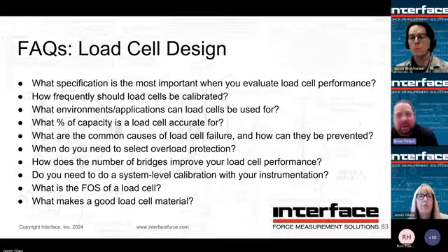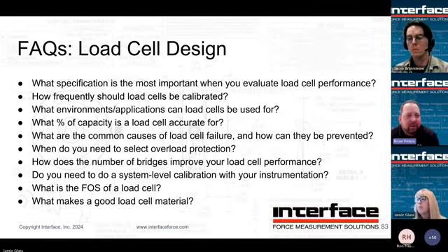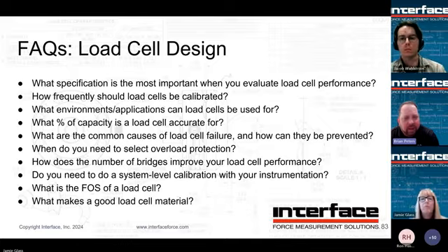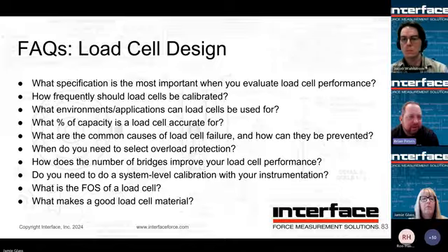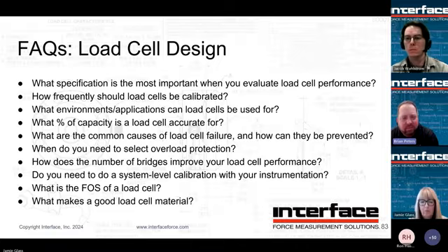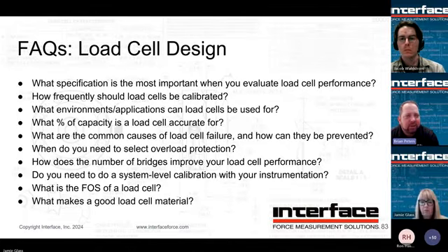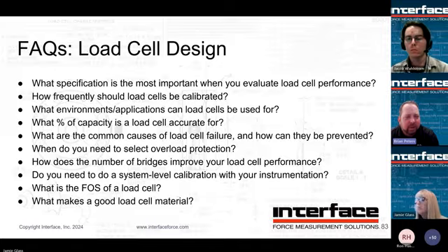we would recommend in-rig system cals if you're concerned about total performance. That's going to take the load cell, the cable, and the instrument all as one system and report it all real time as units in rig in our cal rig. So it really comes down to how much precision do you need, and are you needing to swap out and change from different sensors to different instruments? If things stay paired as a system, then yeah, you can go ahead and get it calibrated that way and you keep that value. But as soon as you change out to a different sensor, there's really not as much value in doing a system level anymore because now it really comes down to the component aspect.